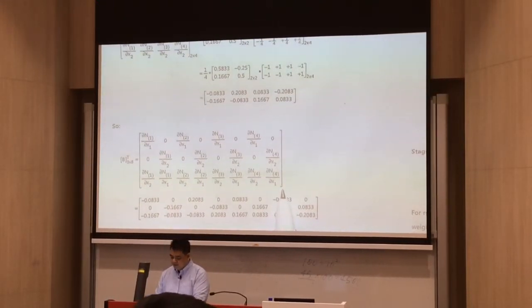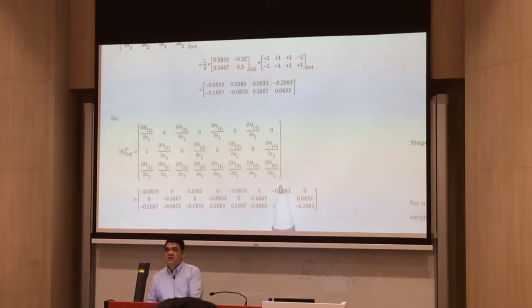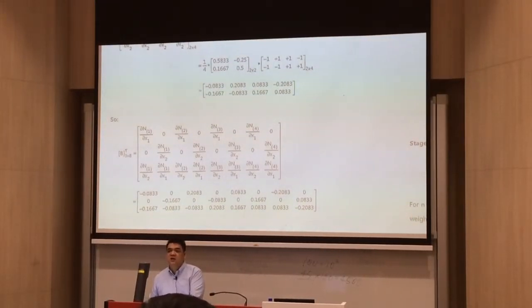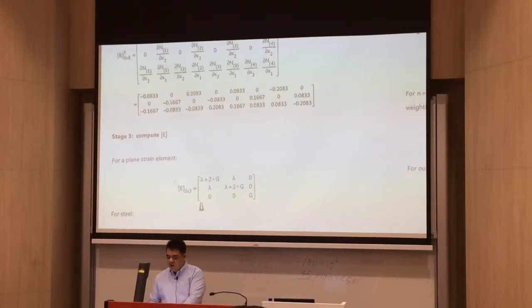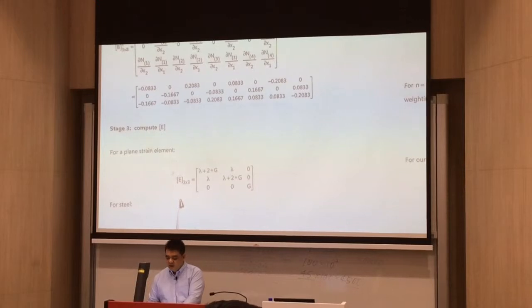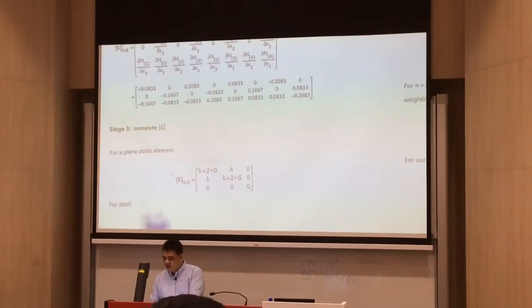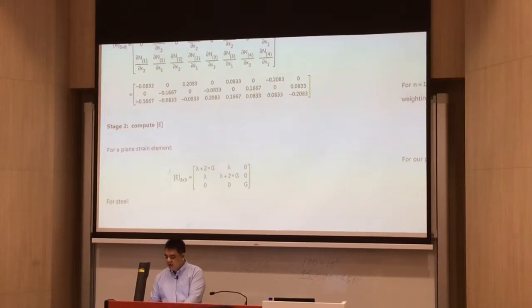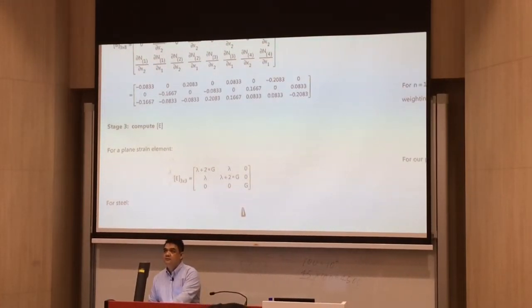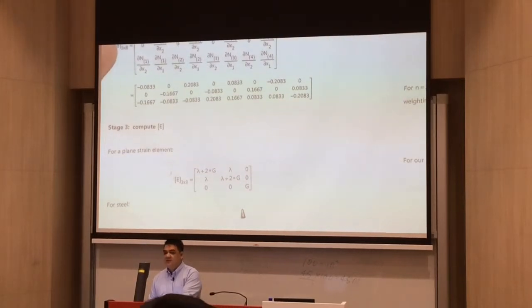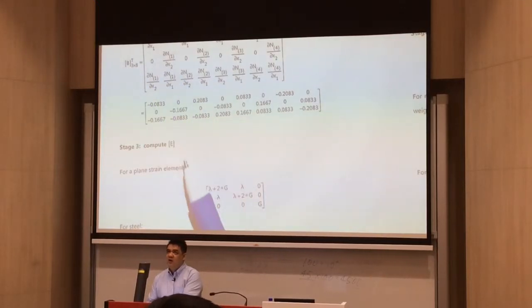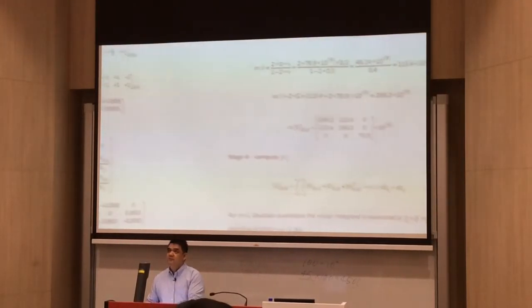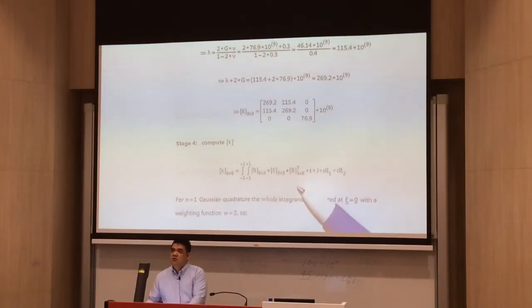Yeah? So not anymore that scary because all of these can be calculated using equations that you have already. You don't have to perform derivation or integration. What about your E matrix? Depending on your assumption, you can use your plane strain assumption or your plane stress assumption. You can calculate for this one. Next, once you have your B, once you have your E, you can now perform this one.